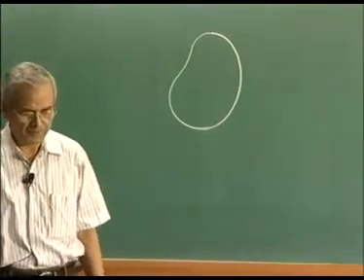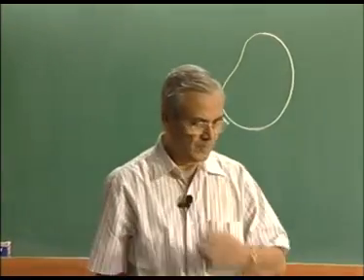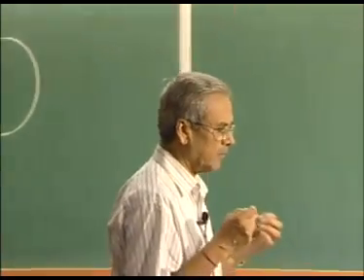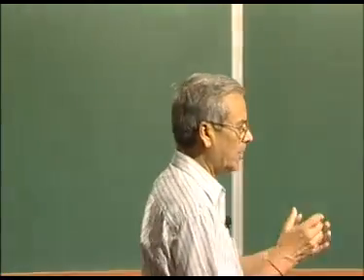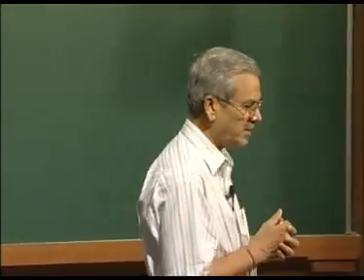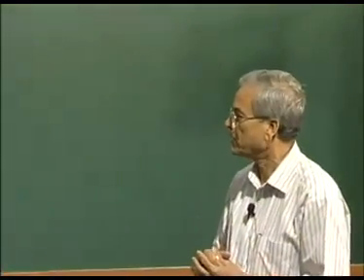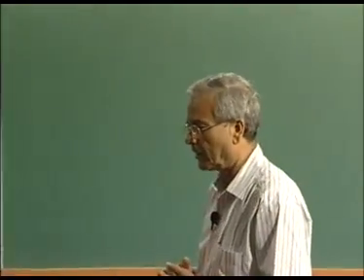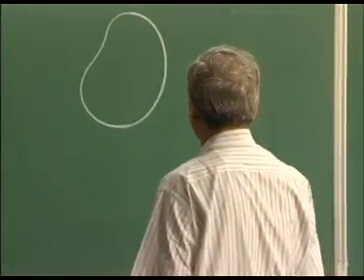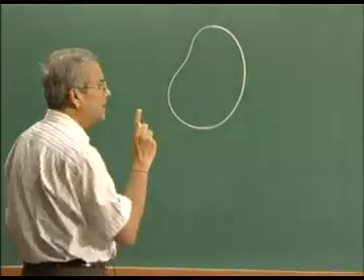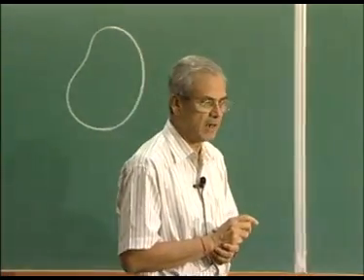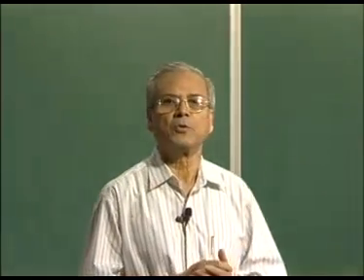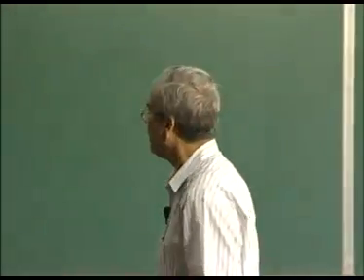So, if this be the rigid body under consideration, its translational motion can be considered to be a particle motion type of motion, where the whole mass of the rigid body may be considered to be concentrated at the center of mass, and the angular motion about the center of mass or any other fixed point O can be represented by an instantaneous angular rotation about an instantaneous axis which changes its position both relative to space and time.